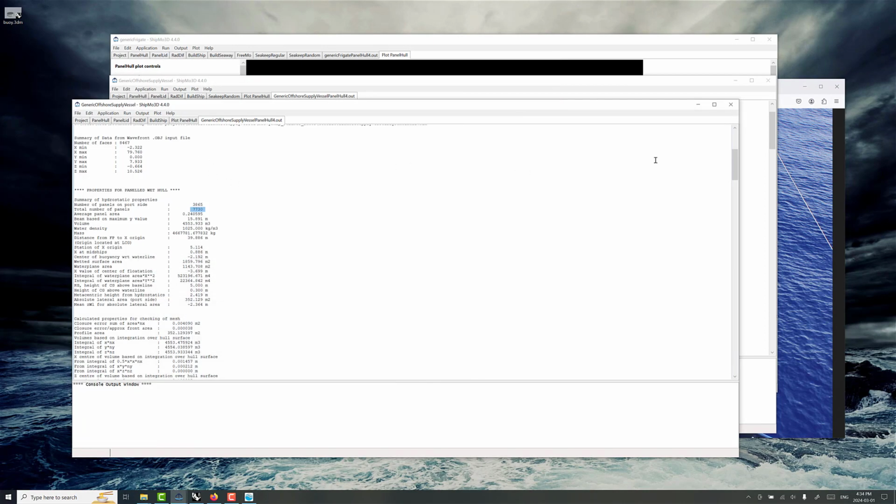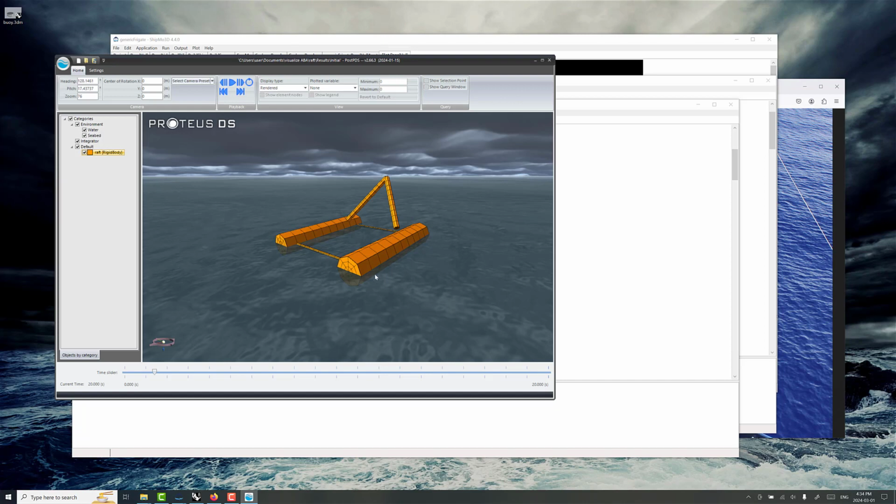That's just giving you a few examples, but ultimately it all comes back to your application. If you're really worried about the number that you have, what you can do is change the number of panels you're using and run a sensitivity analysis. Either increase it or decrease it, see what happens to the motion, and whether there's a significant difference.